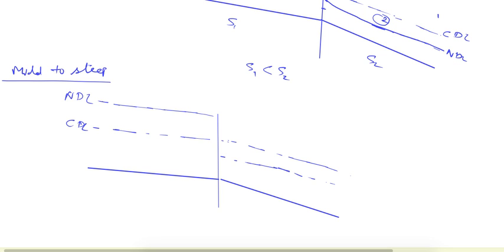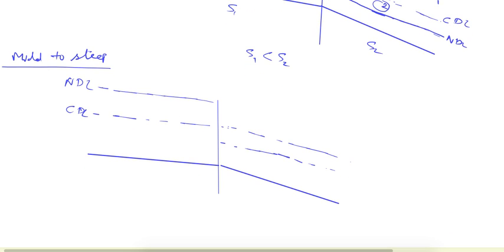Now here we will see two profiles, because the flow before the control section is subcritical, and after the control section it is supercritical. In this situation, because the downstream is the control section for subcritical flow and upstream is the control section for supercritical flow, both of these areas will be affected.